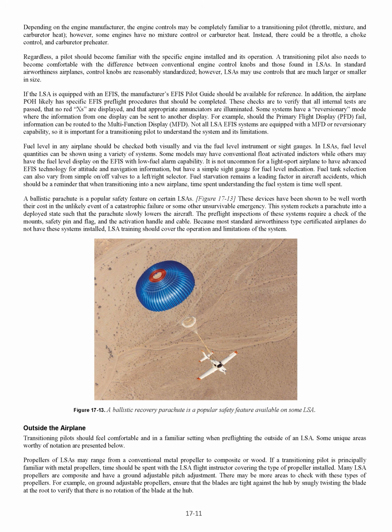A transitioning pilot also needs to become comfortable with the difference between conventional engine control knobs and those found in LSAs. In standard airworthiness airplanes, control knobs are reasonably standardized. However, LSAs may use controls that are much larger or smaller in size. If the LSA is equipped with an EFIS, the manufacturer's EFIS pilot guide should be available for reference. In addition, the airplane POH likely has specific EFIS pre-flight procedures that should be completed. These checks are to verify that all internal tests are passed, that no red X's are displayed, and that appropriate annunciators are illuminated.